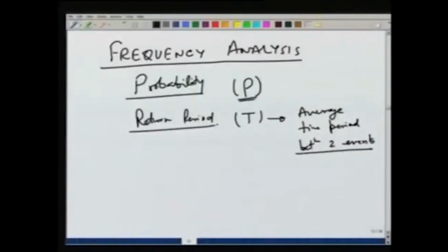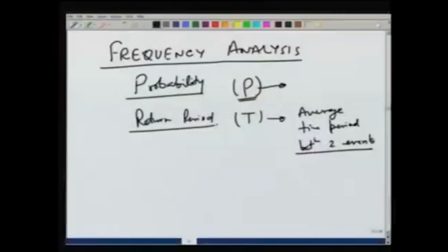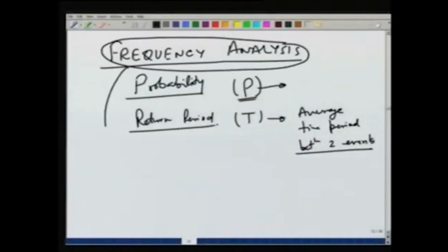Generally, we will talk about annual rainfall values, and probability of occurring in 1 year. What is the probability that the event will occur in a certain period? The way we obtain this frequency distribution is generally what is known as a plotting position method.